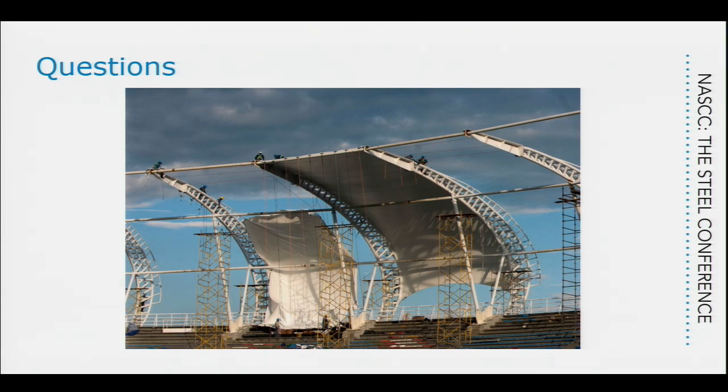No, what happens is it's a hard question to answer because, for example, Serge Ferrari is one of the manufacturers, one of the largest in the world, and they have over 200 materials. So they have something that'll last 2 years, that is kind of a temporary thing. That material is closer to a balloon. You can stretch it by hand. And then you have the Denver Airport type of membrane, where it's very, very strong and you can't move it if you tried. So the variation in elongation is a lot between the manufacturers and between the materials.